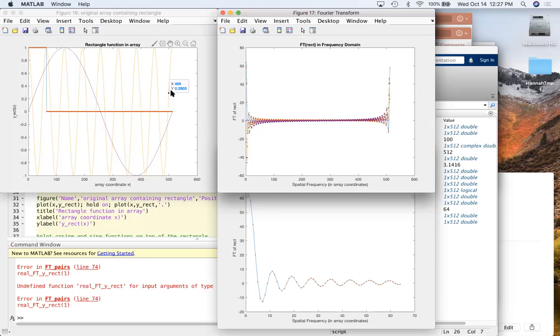It's the sine wave that has that frequency. The cosine wave that has that frequency is this one, 256. That sine wave, when you plot it, is just 1 point up, 1 point down, 1 point up, 1 point down, right? And that's the highest frequency we can represent in this finite array.